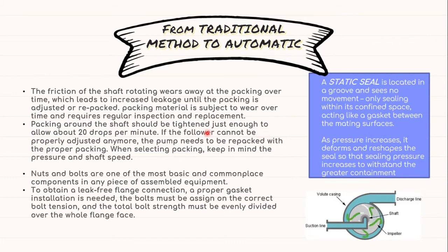If the follower cannot be properly adjusted anymore, the pump needs to be repacked with the proper packing. Nuts and bolts are one of the most basic and commonplace components in any piece of assembled equipment and can be considered as the traditional method. To obtain a leak-free flange connection, a proper gasket installation is needed.